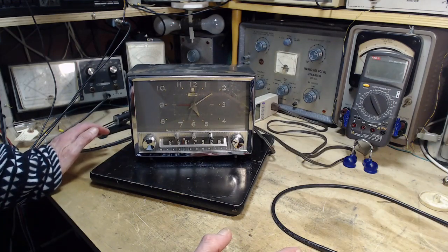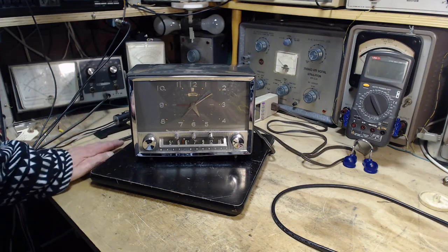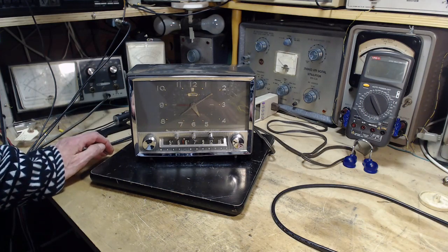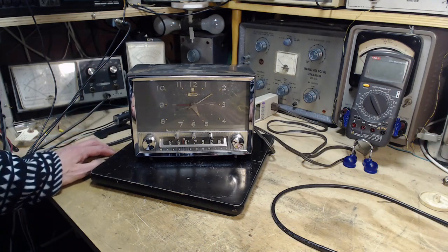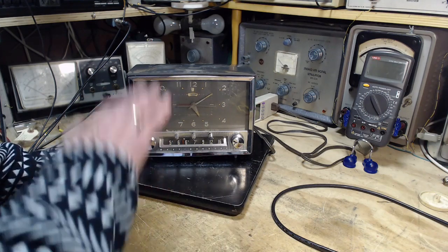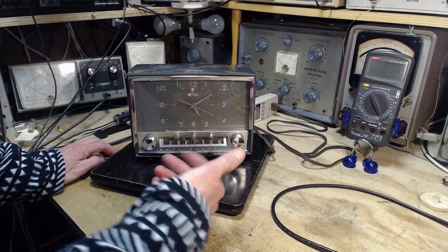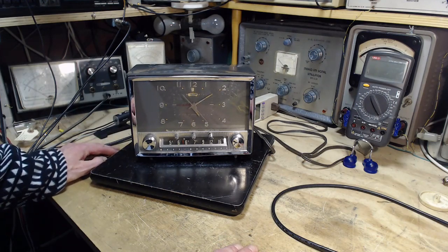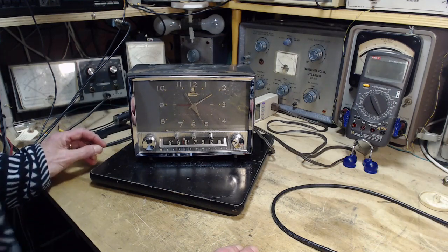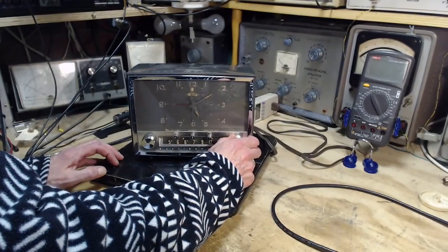The feedback produces a signal that does not produce anything out of the speaker. You can't tell it's there, really. Maybe you can tell a little bit. If the IF is oscillating and the oscillation strength is going up and down, the AVC will go up and down as you tune around. You would notice this, but practically speaking, I think a problem like this could be in a radio, and the only way to really detect it is this heterodyne sound.